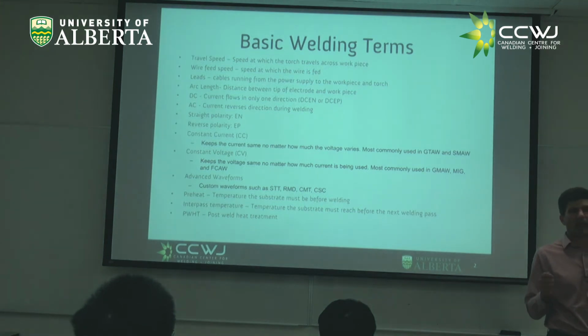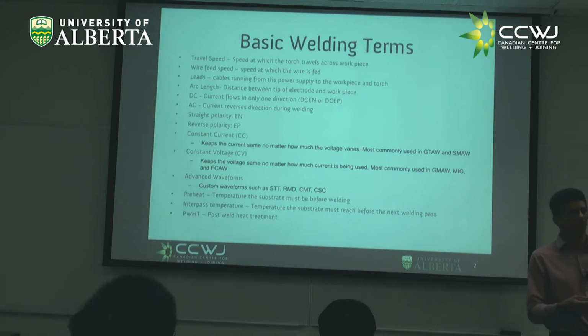Okay, so you weld and you have a hardness problem. What do you do? A heat treatment. You go back to austenite and you normalize, and now you have the microstructure you really wanted to have. But now you have a trade-off. You save the money of a very high preheat, but you have to spend the money on a post-weld heat treatment.